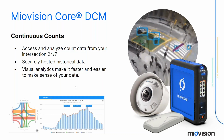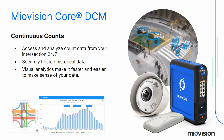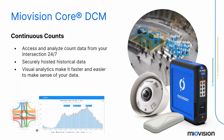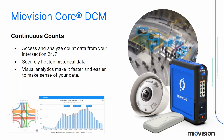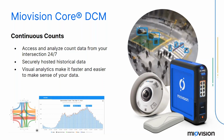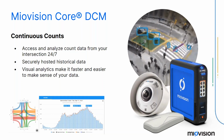So the second application that is the big driver of this device is the counts application. And if you're familiar with our Scout product, Myovision built our company around its ability to provide accurate counts from video. We're able to do it 24/7, 365 as a permanent count station, as well as a detection for actuation system. And you can see it detecting and classifying at the same time. This allows us to get a continuous count, and you can see a chart on the bottom left with the profiles throughout the day, as well as all the classification and the turning movement count diagram on the left that you may be familiar with from the Scout product.